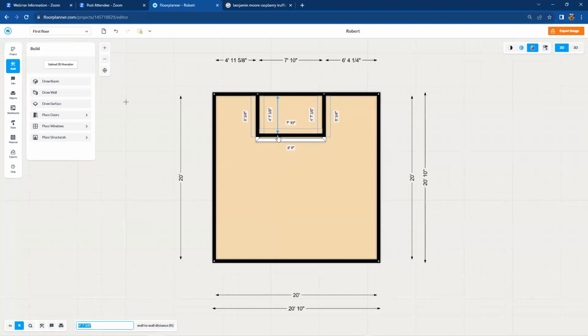Now, pushing it upward and that blue line with the 2 arrows, notice the number changing in the lower left-hand corner, the blue number in that box that we were looking at earlier. If you're comfortable doing this two-handed, still I'm holding my right-hand mouse, pushing that wall upward. I can type in 2 feet on my keyboard and hit enter. And I push that up 2 feet.